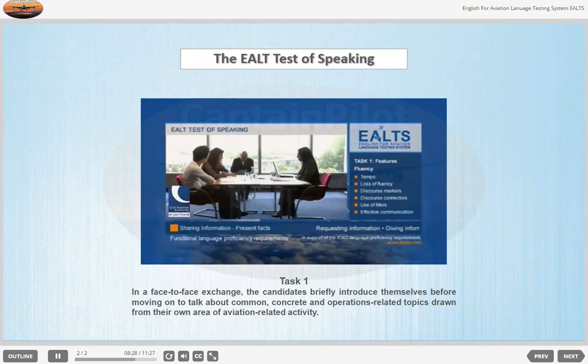And at 12 nautical miles from touchdown, we reduce aircraft speed to between 160 and 180 knots. Then they must maintain 160 knots from, I think, 8 DME to 4 DME from touchdown.